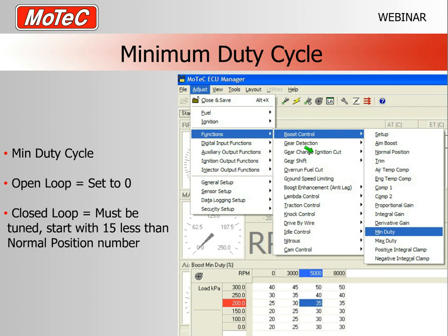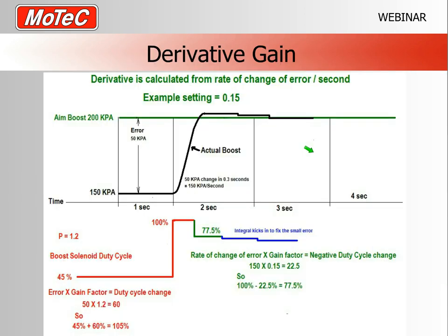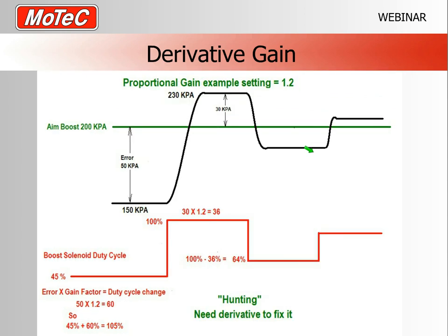So, that's PID. Now, to help with PID and how the system operates, we can actually clamp how much room we give it to move. We can clamp the minimum and maximum duties that the system uses. So back here, where in my example it used 100, the reality is it doesn't need to use anywhere near 100 to get to what it wants. So you can clamp it back using a minimum and maximum table.